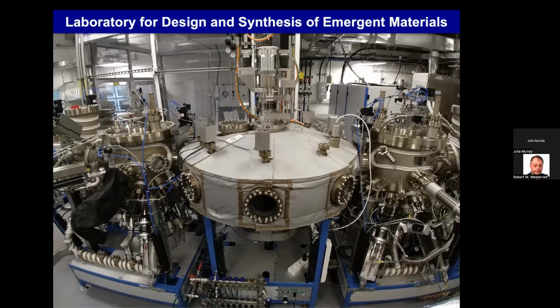In principle, though, if you brought me a 4-inch silicon wafer, I could put it into the chamber on the holder. That's what it's made for. So that's the lateral size, and how thick it is depends on the research project. Some projects are literally trying just 1 atomic layer. Other projects you might want 500 nanometers, which is about 5,000 atoms tall, or even a micron. We grow at about a monolayer a minute, roughly. We can do 2 monolayers a minute, but that's rough order of magnitude.